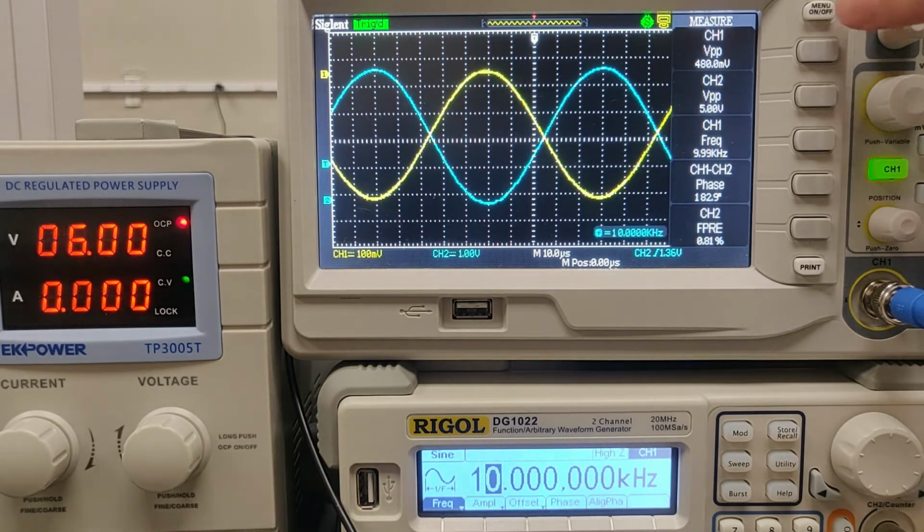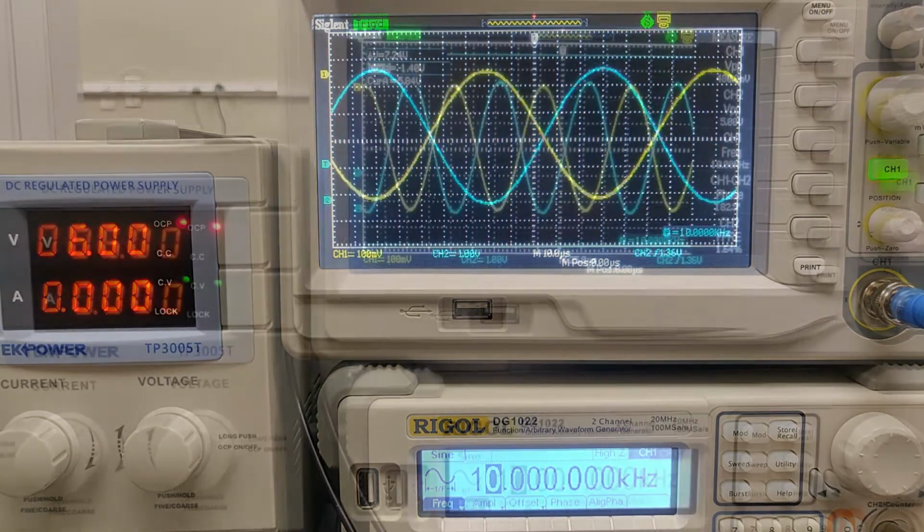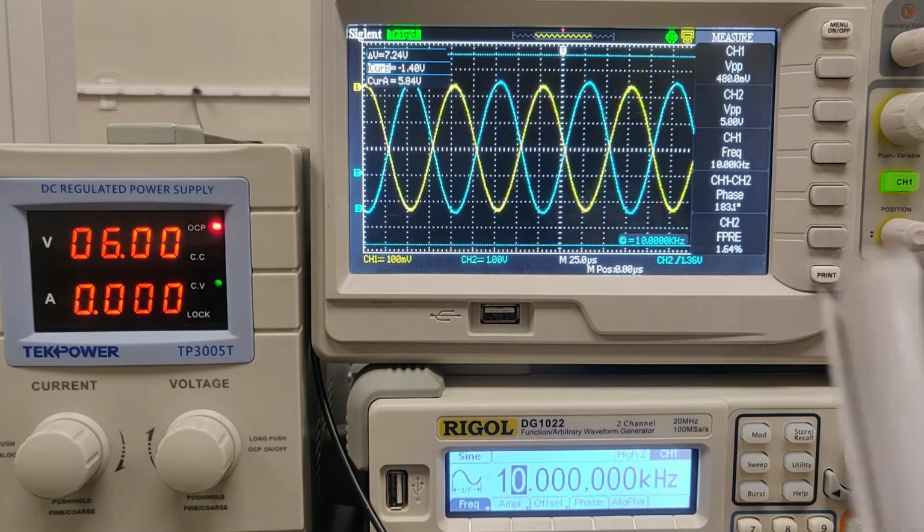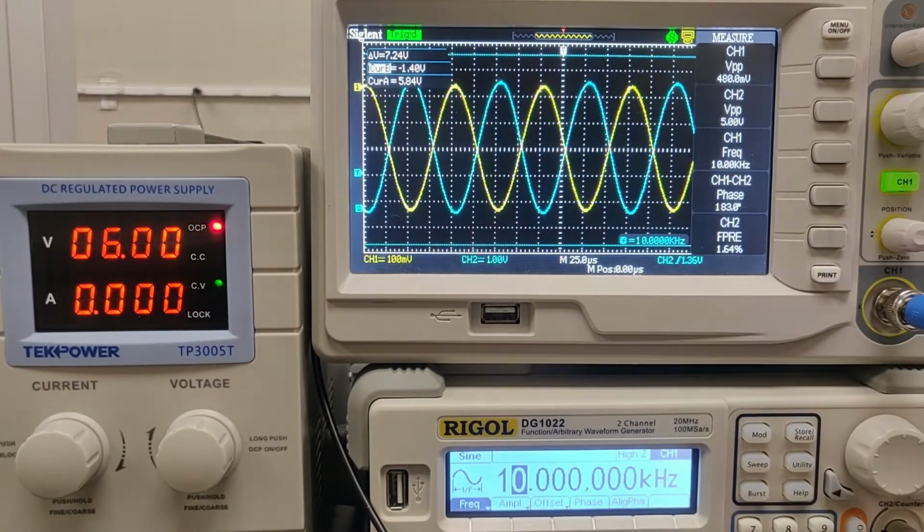Now let's find the cutoff frequency. All right, so if our maximum gain is at 10.42, then at the cutoff frequency our gain should be that times 1 over root 2, which is 7.36. And assuming that our input voltage stays around this 0.48 mark, I think it'll probably increase slightly, but we'll just use 0.48 for right now.